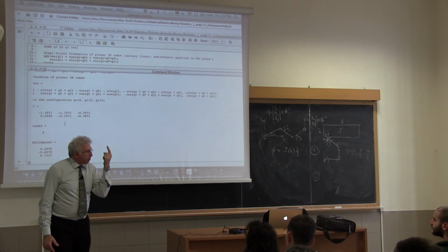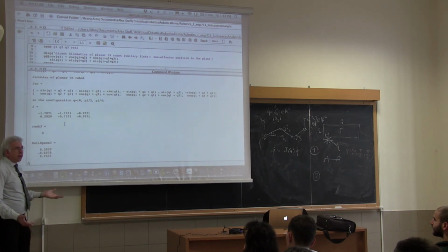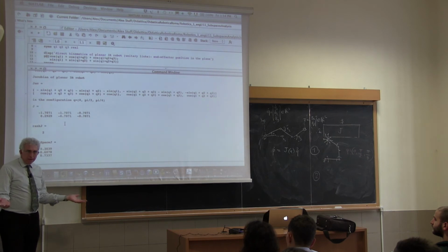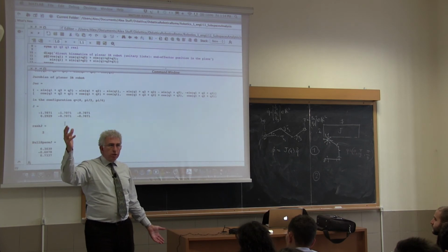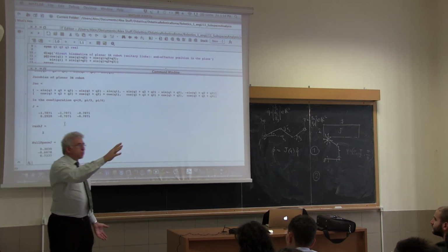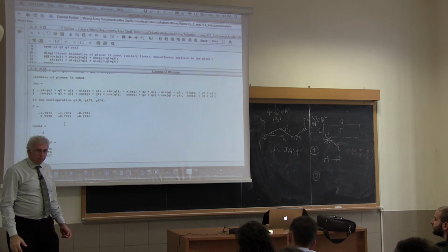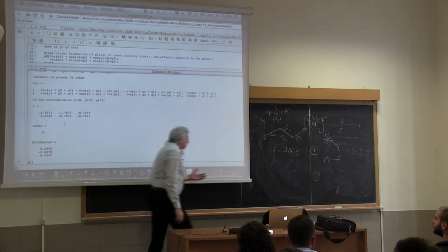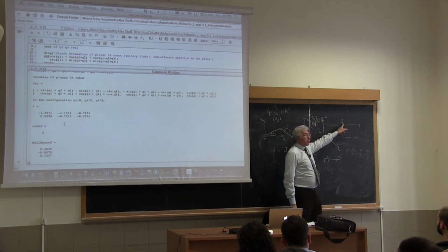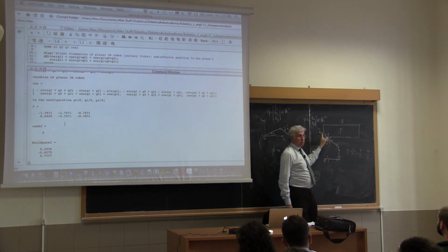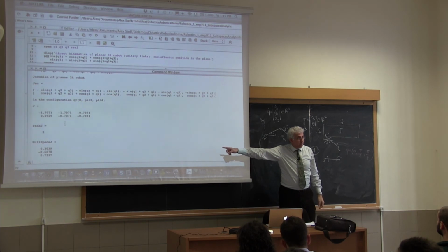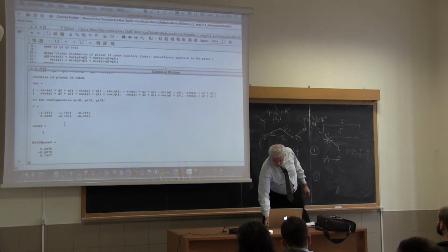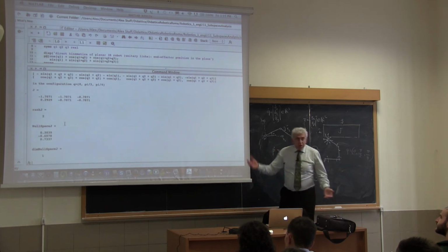But this is not just one velocity, because if you multiply this by a factor alpha, it's exactly the same. Okay? So there is a one-dimensional subspace of joint velocities that do not produce instantaneous Cartesian velocities. And this is so because this is full rank and this has 3 columns, and in fact the difference between the number of columns and the rank is exactly the dimension of this null space. Okay? In fact, the dimension of the null space is 1.